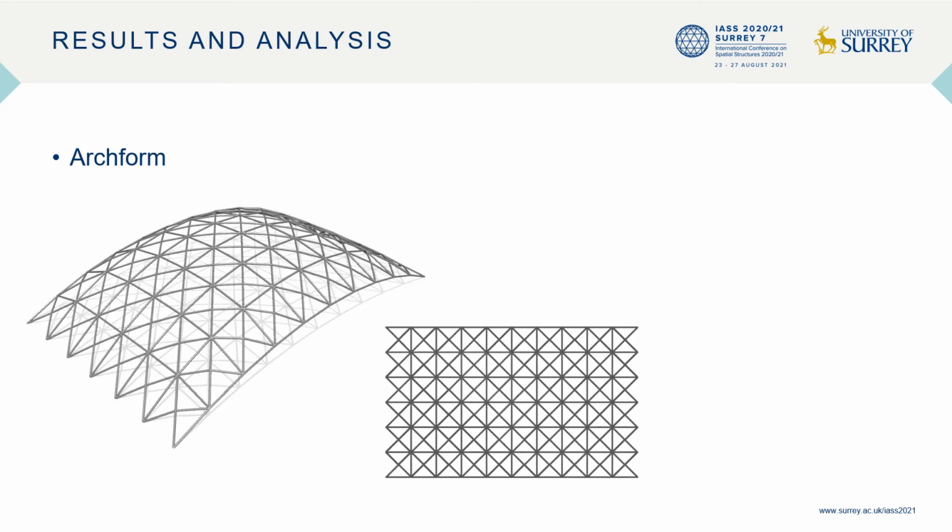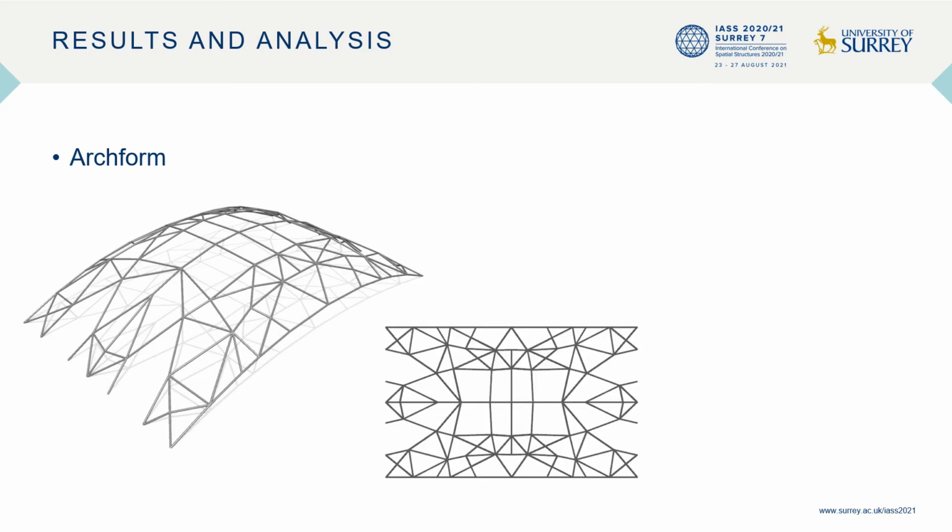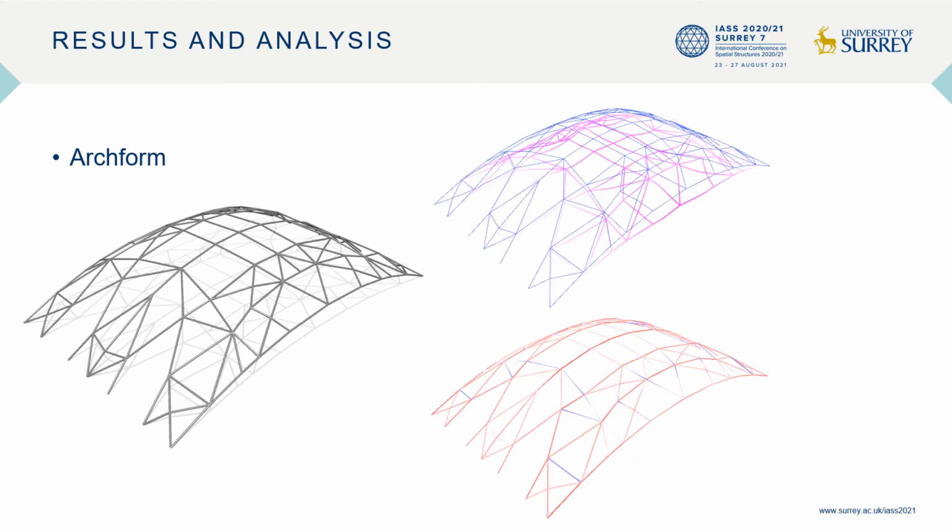The Scottish mathematician and biologist Darcy stated that the form of an object is a diagram of forces. This is very much also the case for this result. We can see that the algorithm adapted to the affecting forces by creating these braced legs to transfer the vertical forces to the ground. This pattern is so effective that only 2.4% of the strain energy originates from bending forces.